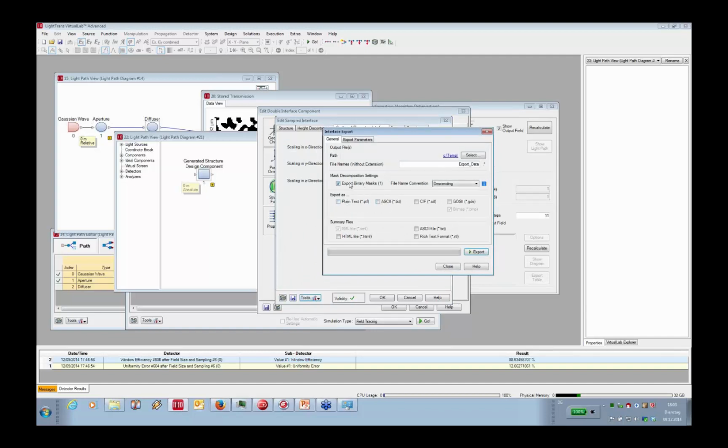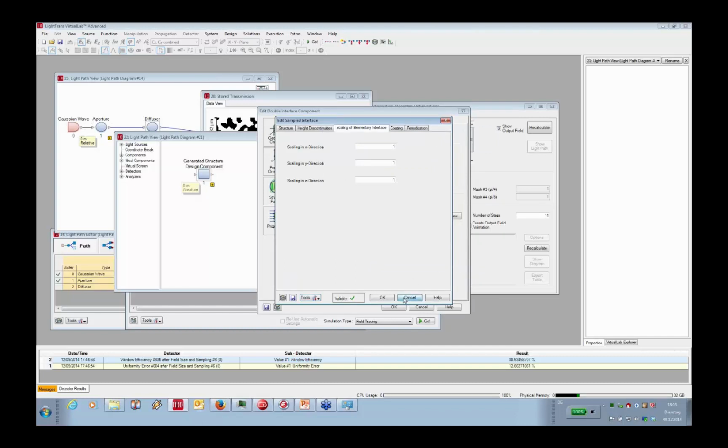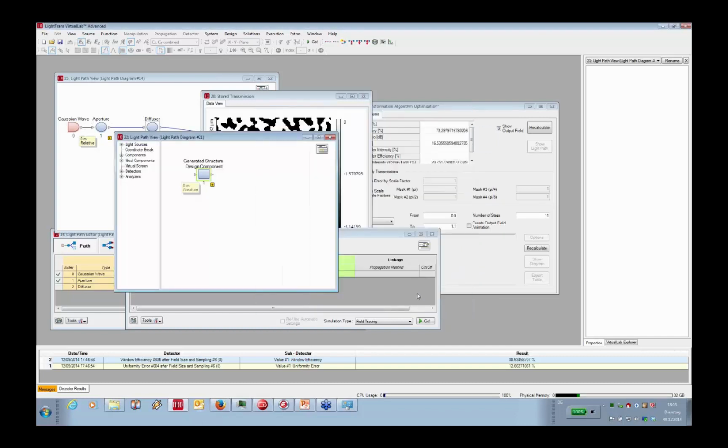You can generate or calculate an etching mask. If you have a multi-level element, you can generate GDSII and CIF or bitmap files. Especially CIF, GDSII and bitmap file formats are often used for the etching process, especially GDSII and CIF files. These are vector data files that come from microelectronics, and they are typically also used for micro-optics. So VirtualLab can calculate a different etching mask in the case of multi-level elements, and can export this etching mask in different file formats.